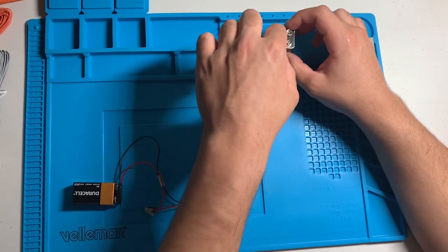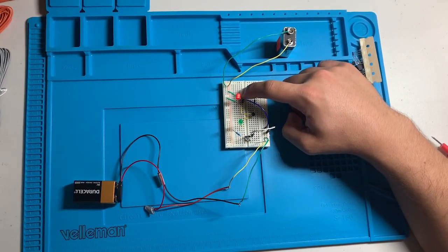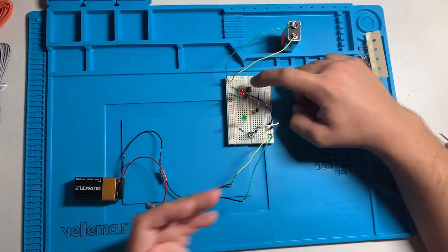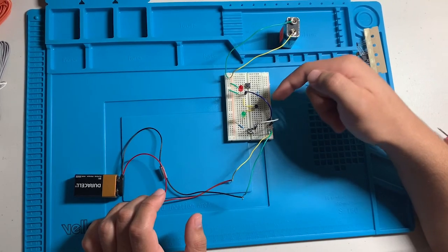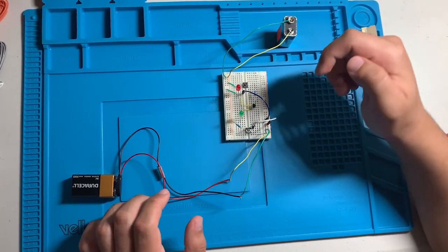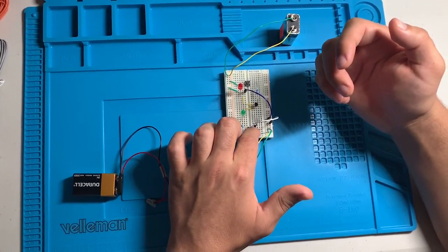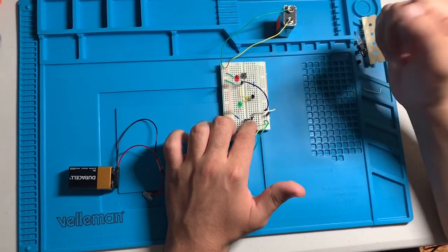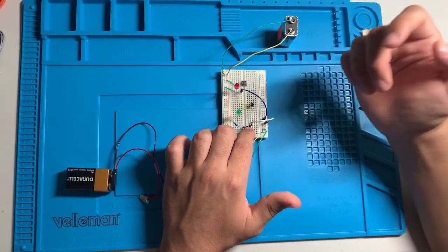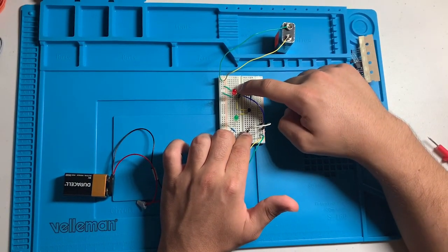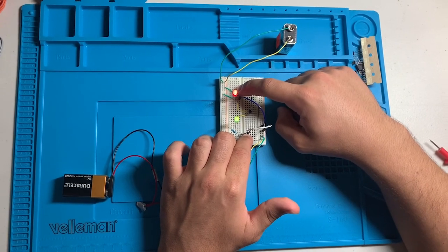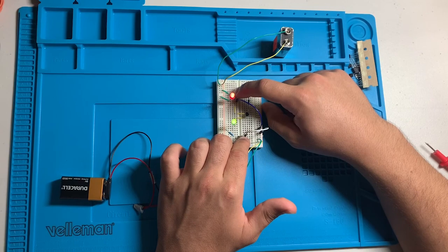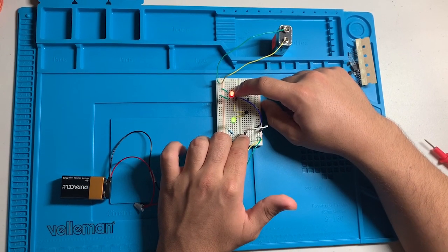What we notice first off, we turn this on, and we have the red LED flashing because the current is flowing from the base through the emitter through the red LED. And then if we try to turn on this loop, nothing happens because the transistor acts as an open switch. So what we can then do, turn this on, turn the other switch on, and the current flows all the way through from collector to emitter thanks to the semiconductors, and the circuit is complete.